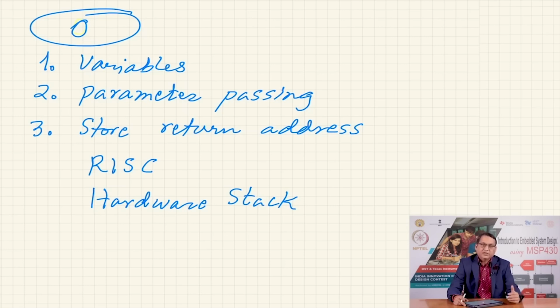When does the size of the stack grow? When you call a subroutine from within a subroutine from within a subroutine, what are called nested subroutines. When you have too many nested subroutines, they would increase the size of the stack. As you return from a subroutine, it would vacate the stack, and therefore the stack size would reduce.